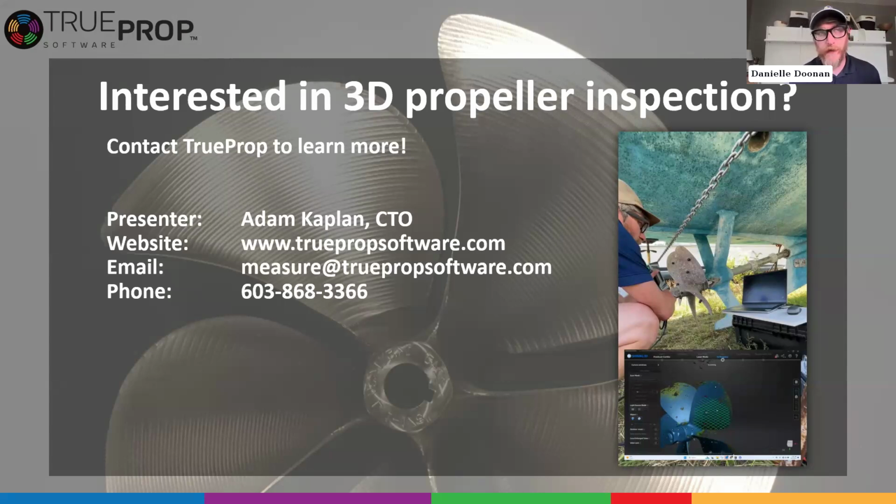So the only thing with the Raptor X, again, you've got to use scan spray. The tracking can be tough, so you've got to use a lot of markers. The field of view is small, so it may take a while to scan a 40-inch prop. And it has some recommended volumetric accuracy, like it may only go up to maybe 50 inches or something like that. But yeah, it's a great entry-level scanner. It makes it extremely affordable to get into this. And I generally tell people to not buy the Cadillac as your first car, right? You can work up to this, and that's some of what we have.